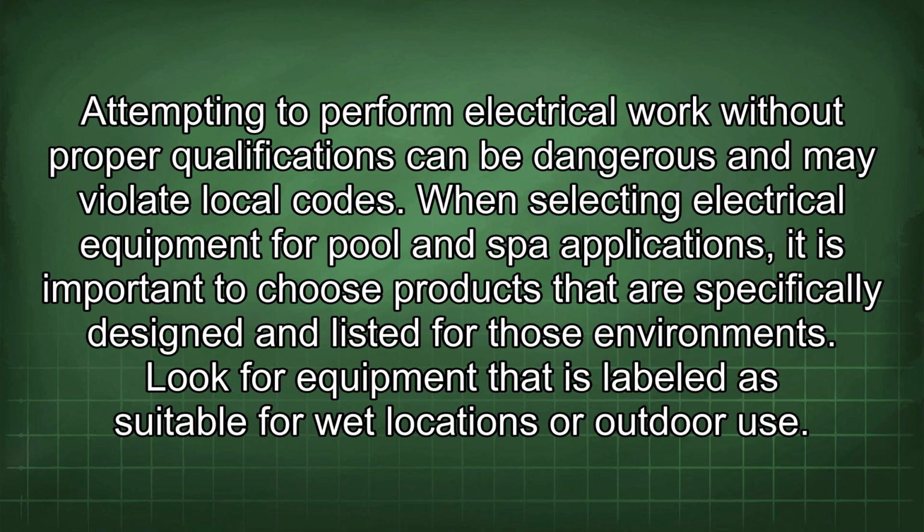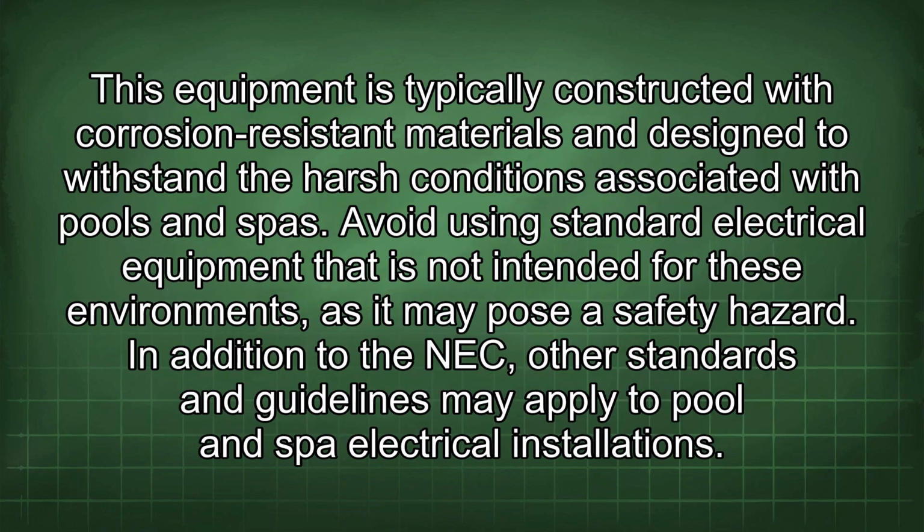When selecting electrical equipment for pool and spa applications, it is important to choose products that are specifically designed and listed for those environments. Look for equipment that is labeled as suitable for wet locations or outdoor use. This equipment is typically constructed with corrosion-resistant materials and designed to withstand the harsh conditions associated with pools and spas. Avoid using standard electrical equipment that is not intended for these environments, as it may pose a safety hazard. In addition to the NEC, other standards and guidelines may apply to pool and spa electrical installations.